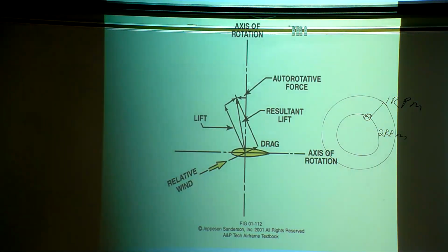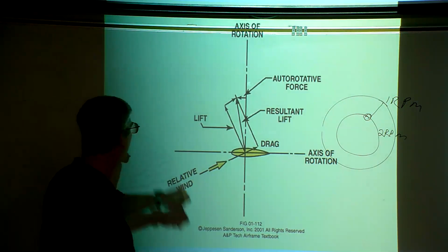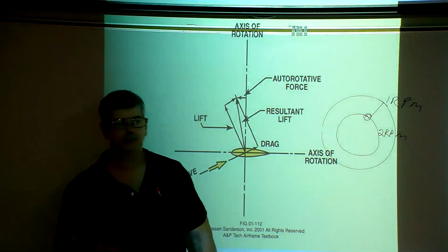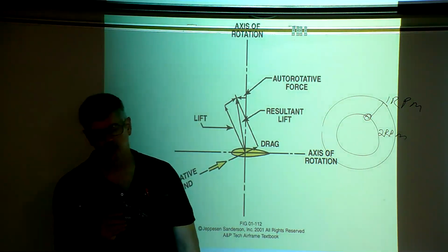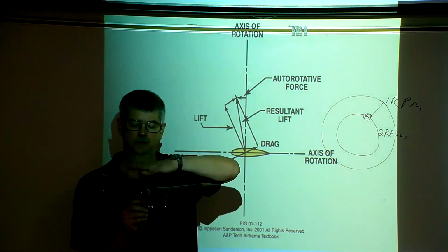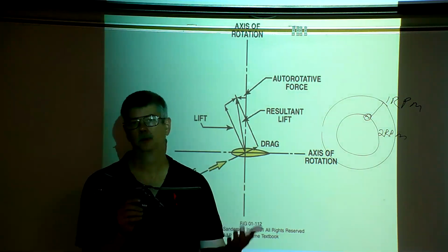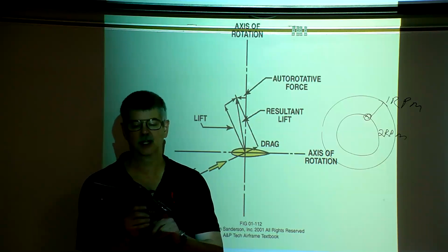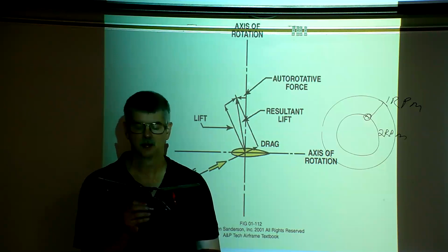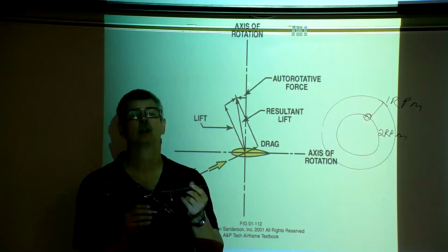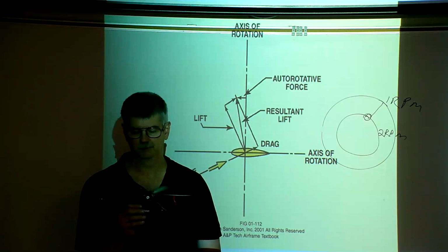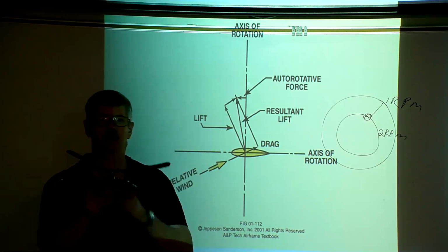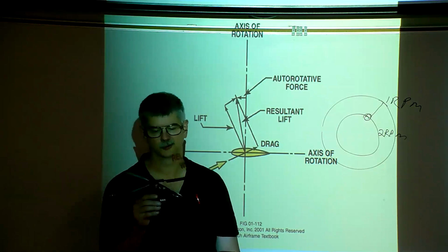It's crazy, all the diagrams that they try to show, but for autorotation, if we have an engine failure, the rotor blade will keep turning. It's on what's called a freewheeling unit. And what that means is that the engine can turn the rotor blades, but if the engine stops, the rotor blades keep on spinning. All right. So that way, if anything happens with the engine transmission, the rotor blades will freewheel.